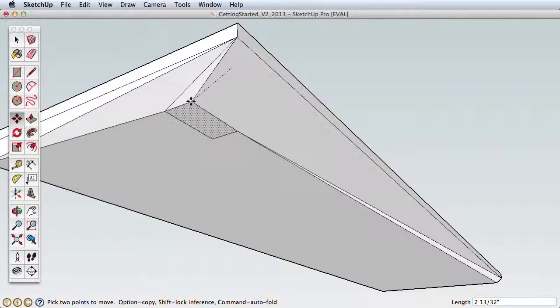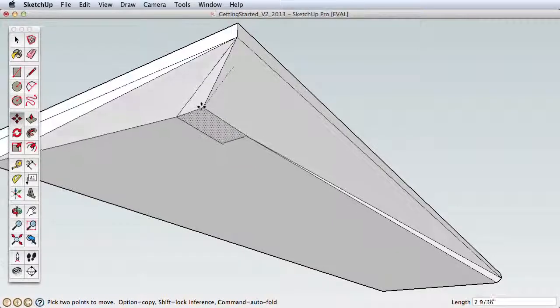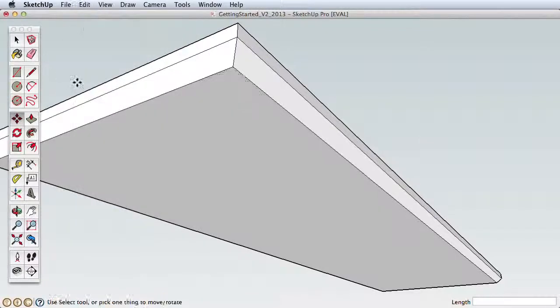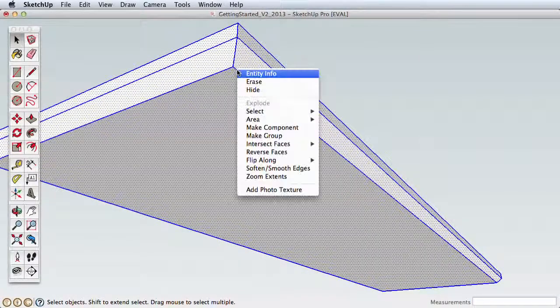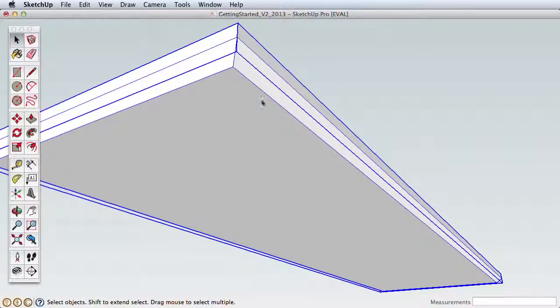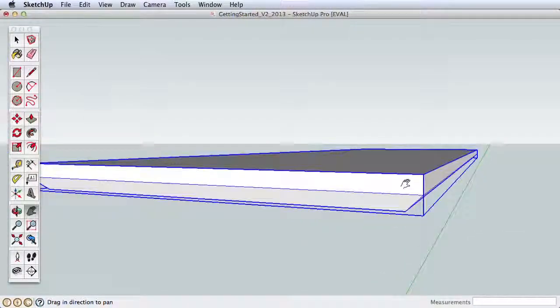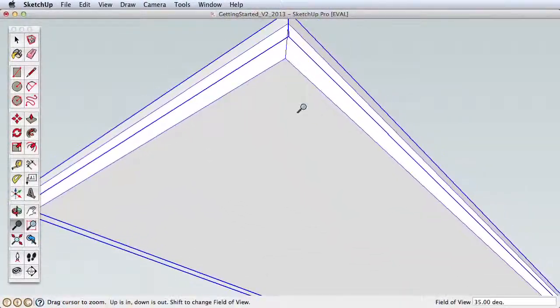This is one of the primary uses of groups, which will isolate our geometry, preventing the edges from merging. To see this in action, undo the rectangle, then triple-click to select the whole tabletop, right or context click on the top, and from the submenu choose Make Group. A new bounding box is shown around the whole top, and it now behaves as a single, unique entity.